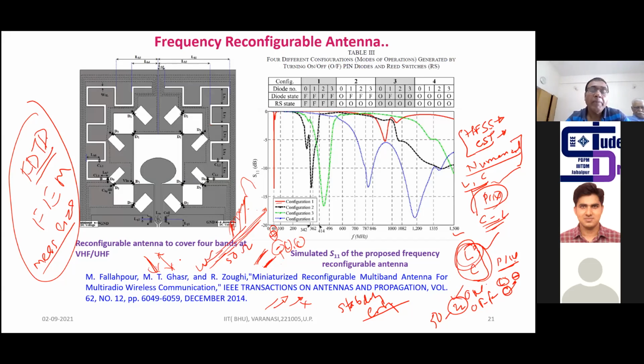What is happening? Based on the machine performance, your simulation software optimizes and adaptively makes the meshes, based on the RAM. When the software finds a good machine, it redefines the meshes, adapting the process, and the mesh size reduces. So stability depends on the mesh size. If you decide your open region and boundary condition, change the boundary condition, and the results are the same without any change, then you can say your results are very stable.